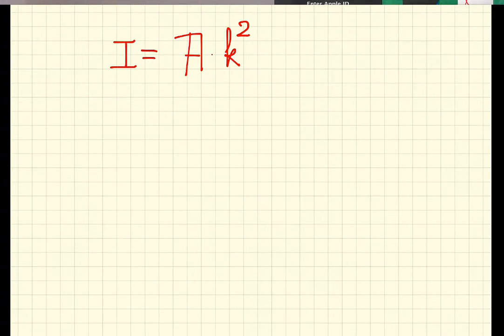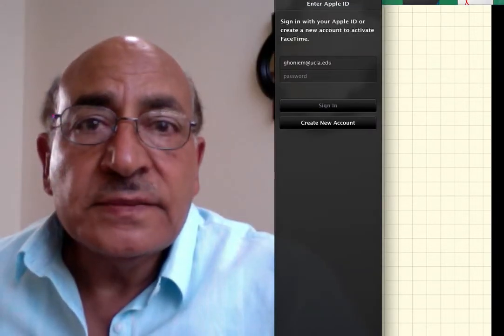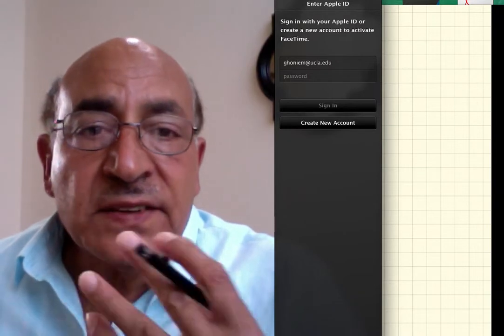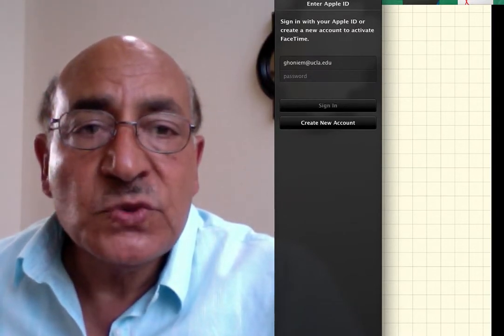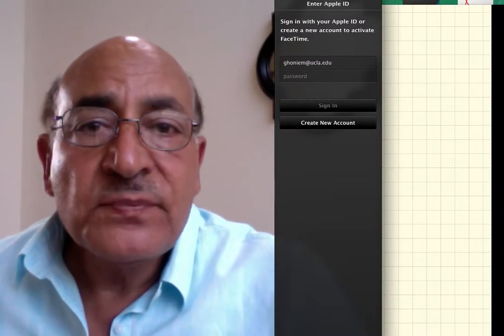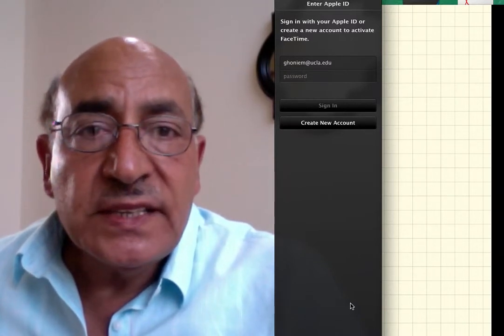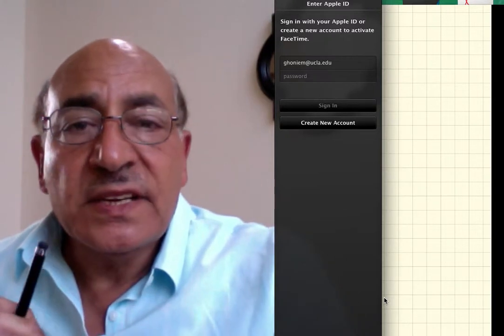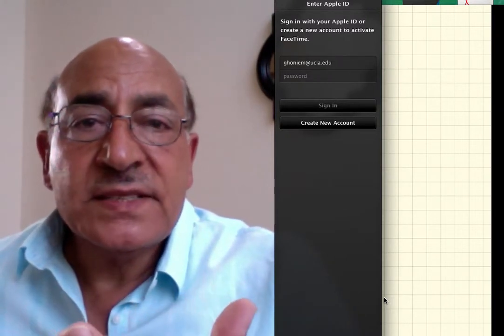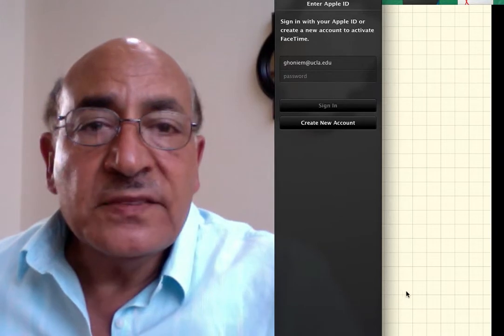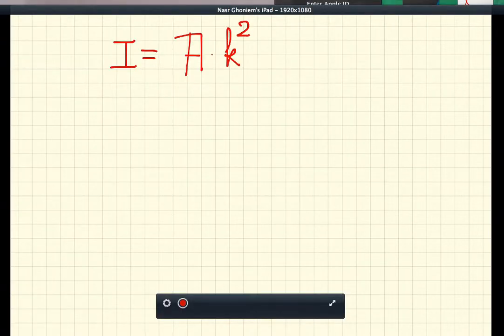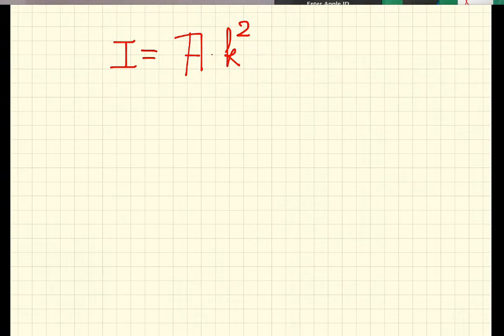The reason we do this definition is that, number one, it came from dynamics of rigid bodies, radius of gyration: the member, if it moves, then it moves with that radius. Number two, it's really useful because we can convert the second moment of area to a cross-sectional area times an effective radius squared.